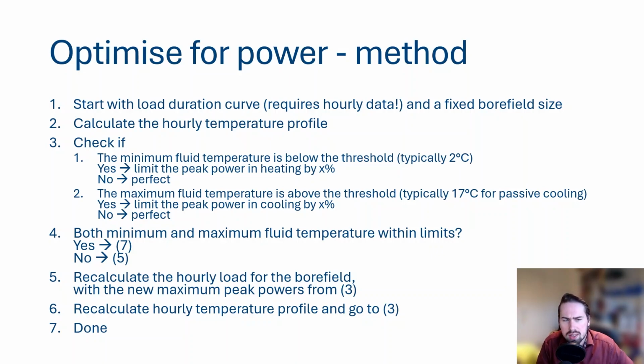So we do these checks, and then we go to step 4, where we see, well, are the minimum and the maximum fluid temperature within the limits? If they are, then we're done. Then our total borefield is sized in such a way that we can always deliver our installed heating and cooling power. But if not, then we go to step 5 and we recalculate the hourly load for the borefield,